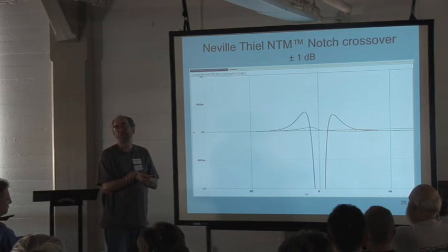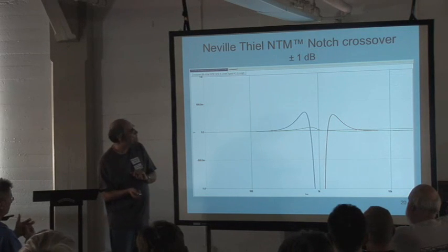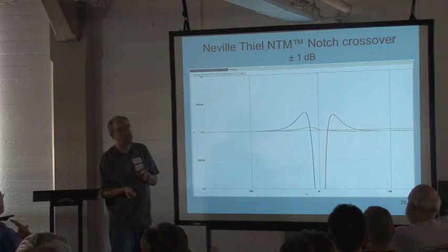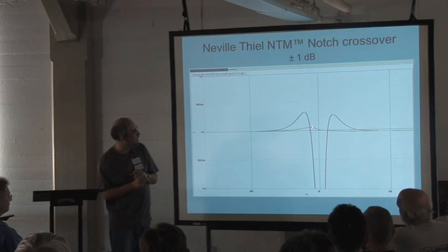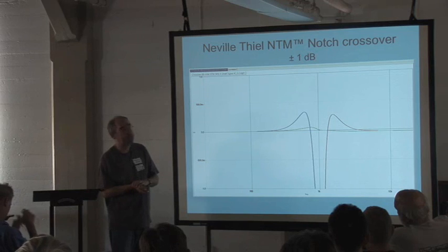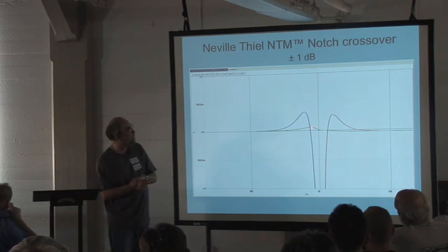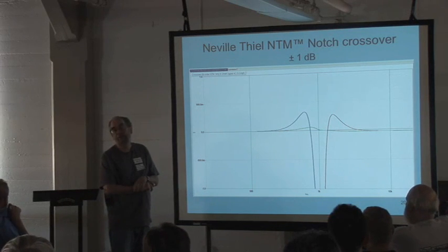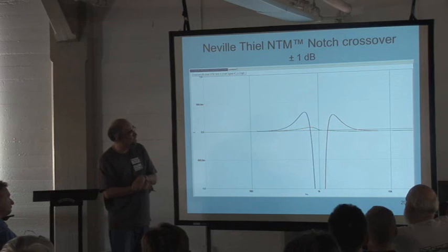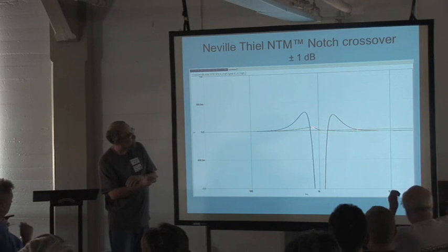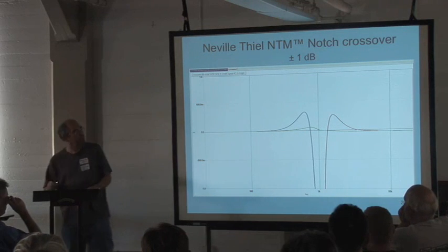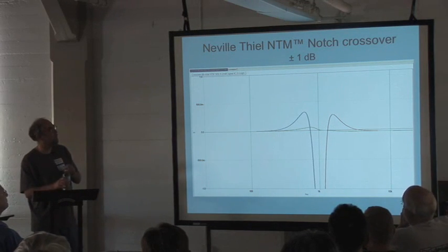My understanding is that this is supposed to sum to exactly flat. But what I did with this, I didn't do the mathematics. I simulated it with real op-amps, with 5532s. And that is what I got. You know, the error there is extremely small. It's less than 1/10 of a dB, which is probably negligible for crossover use. But whether that is due to bandwidth limitations in the op-amps or something else, right at the moment I can't tell you. But as you can see, it's not exactly significant. But the fact it's asymmetrical and it's not the same both sides makes me think that I have screwed up there somewhere. I wouldn't be surprised. Okay, if you'd like to go to the next one.